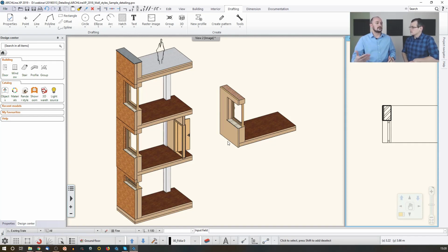That's why ARCHLine is set to be like this by default. You can freely edit any part, and if you don't want to handle this sort of thing, you don't have to. You just type the values and you will be fine. But by default, the software is creating structures bound to level variables, we call them. Just imagine hundreds of walls to be updated manually. ARCHLine automatically makes this change, and whenever you update a large building, ARCHLine is able to respond to that change on the whole level of the building.